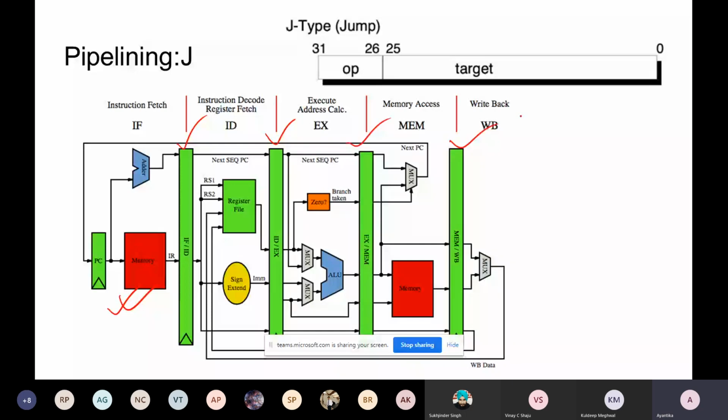For that, the main intermediate part we use is these registers. When we are working directly without any pipeline, some registers we may not use. We can directly send the value to the next level of components. But to implement this pipelining strategy and to support parallelism, we use these intermediate registers. Those are typically pipeline registers that we use to send input to the next levels. But things are not so simple. Do you have any question up to this?